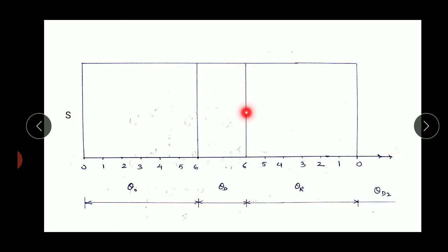So draw a line of 40 mm here and complete the box. From start to end just complete this box and draw the lines at the end of the outstroke and at the start of the return stroke.